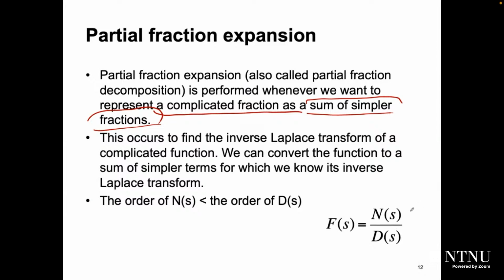Usually in control systems, the order of the numerator should be less than the order of the denominator. If not, you need to apply long division. We applied it in chapter 2, if you can remember. So the order of N(s) must be less than the order of D(s). If not, you need to apply